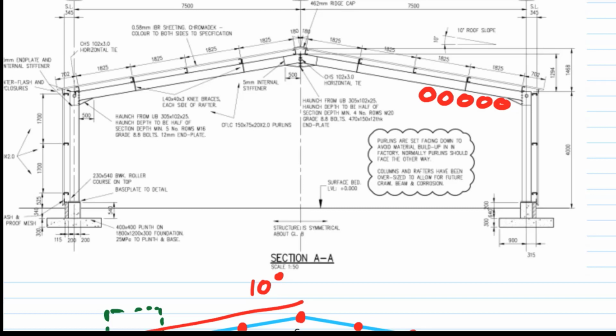So I'm rather going to err on the conservative side and assume it is a live load, so it has a higher factor, but also it can be a factor of 0. So it might not be there, and that's true in such an industrial warehouse. Maybe the process changes and now you don't have any services hanging from the roof, and that can actually resist uplift wind load. So both it not being there or it being there and being more could be the worst load case, depending on what you are looking at. So hence I've taken it specifically for this case as an imposed load.